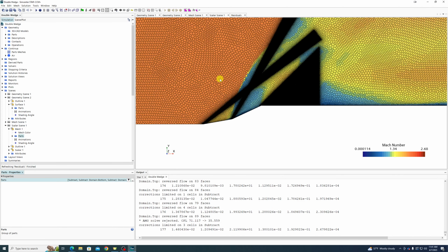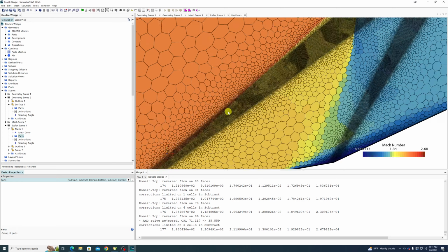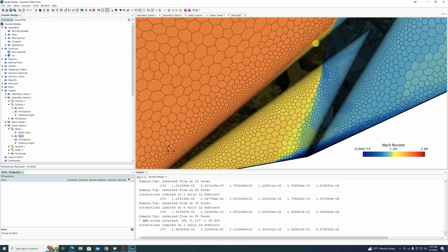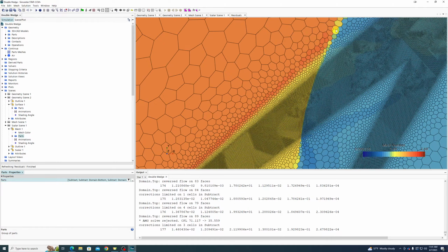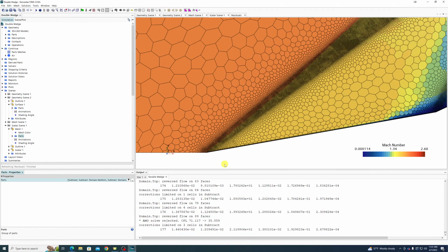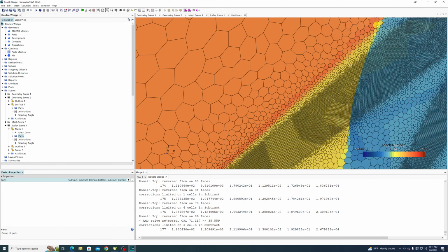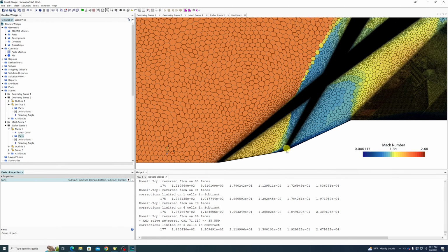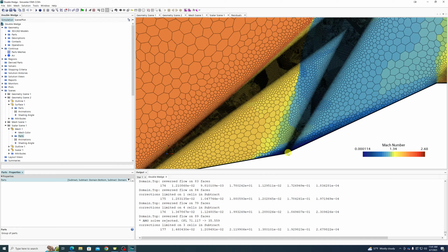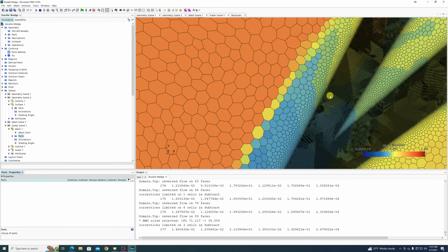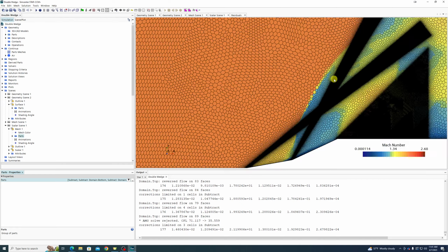It looks like we got that initial shock angle pretty close. It's a little bit off. Notice how this shock, it absolutely starts here. It's almost exactly in our cone, but it walks out a little bit. And this shock angle is way low, actually. It needed to be higher than that.